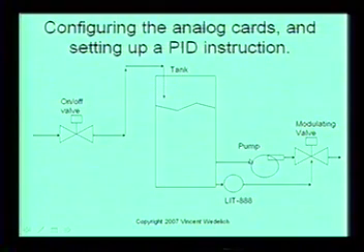I have at least 1 output and 1 input to tell me if the motor starter actually started or not. And then if I have a modulating valve, I at least have 1 analog output, and I'd like to know the position of that valve, so I do 1 analog input. So you can actually look at a diagram like this, and in your mind you can say, okay, I know what I need to build this PLC program or build this PLC control panel.